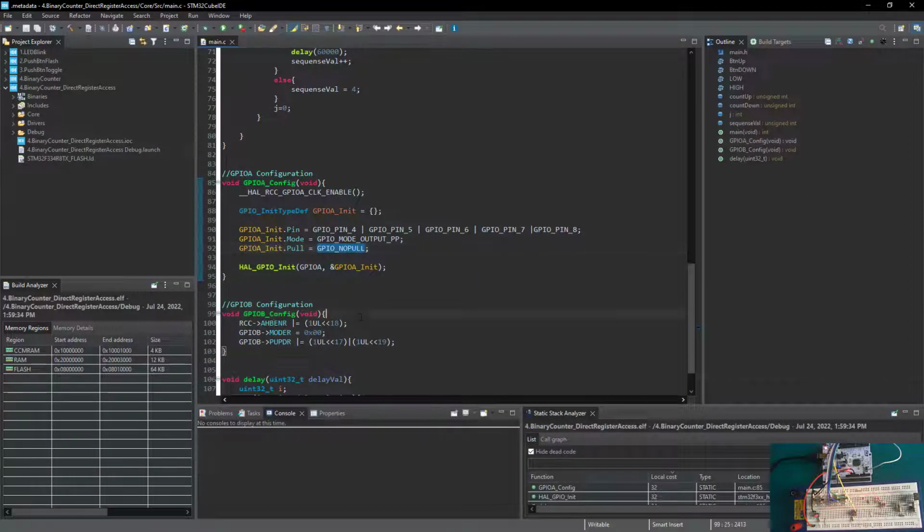So all we have to do is basically just copy this code here, right? Because in programming, you have to be able to copy the correct code in the right place to save you time. So we just replace that with 17, and that will mean the clock on port A would then be enabled. Having said that, we don't need this variable as well.